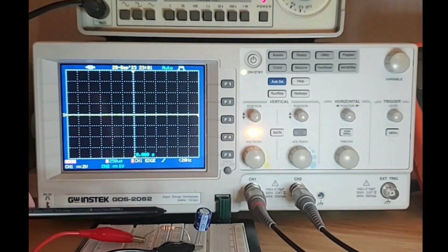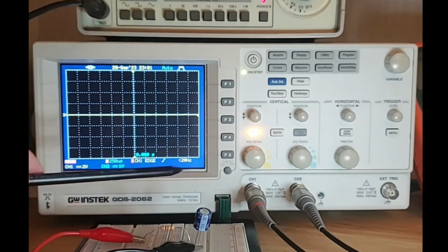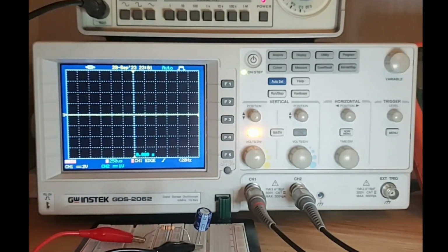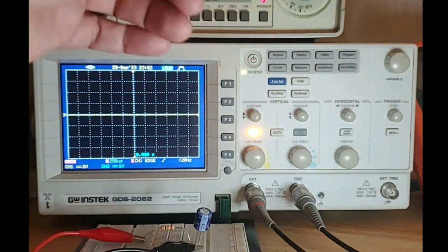Now, based on these values of 1 kilo ohm and 10 microfarad, I calculated that if I use a frequency of about 16 hertz, then the delay in the voltage across the capacitor would be about 45 degrees. So we will have a 45 degrees delay. The capacitor voltage will be 45 degrees delayed compared to the source voltage. So let's see those two, and we can measure the delay or the phase shift. We call this delay the phase shift, and we can see those two together.